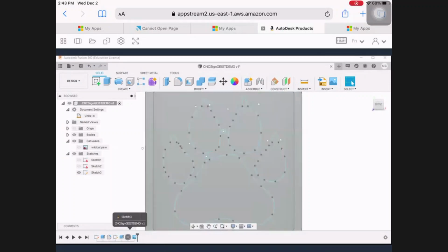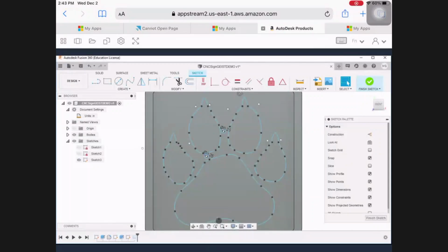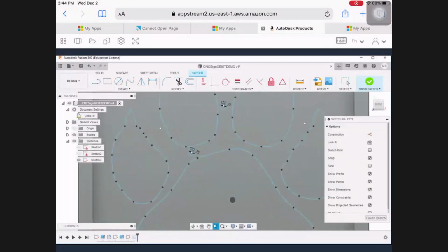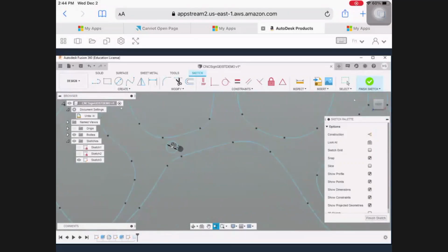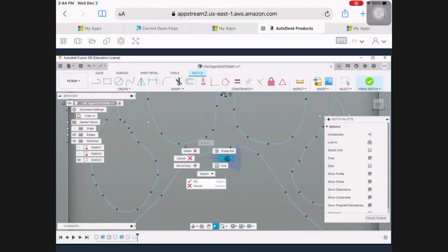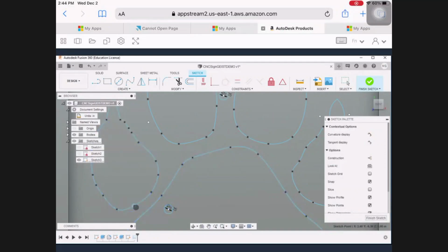and then I'm going to double click in this history and go back into my sketch, because if I come down, I want to see if this tool is going to fit. Because if I come down and I look at this little 1/4-inch tool, right click OK, it's not going to fit here. So the nice thing is I can just grab these lines and I can just move the geometry. I'm basically making room is what I'm doing. And I might want to do that over here, maybe over here, just so that this tool can come in and have some wiggle room, as they say.